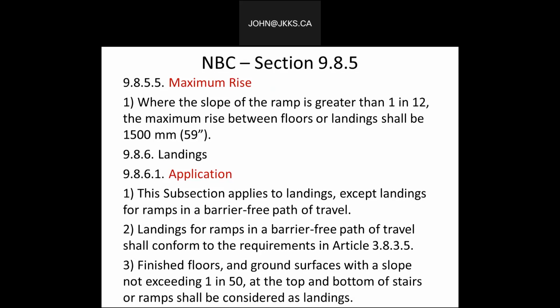So as we go through this, you will see that in longer and more height requirements, we will probably, in most cases, require a landing space. In other words, we don't want long ramps without having landings. So kind of, we'll call it, a transition or a resting spot for the ramp construction.